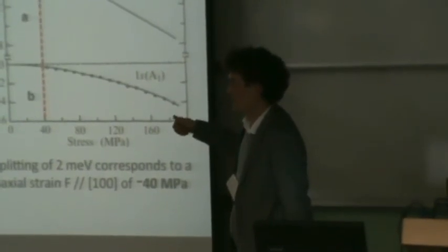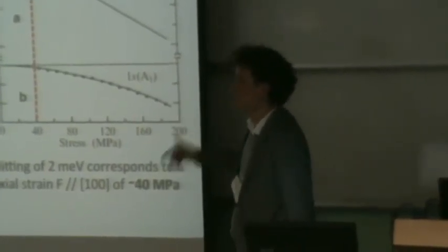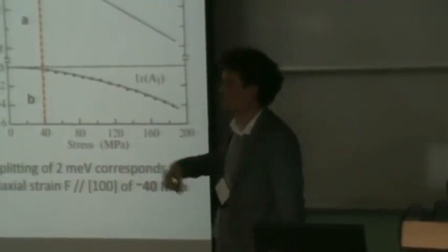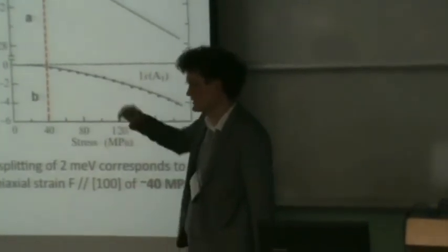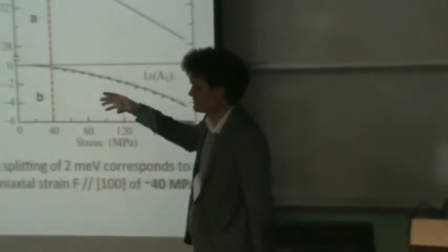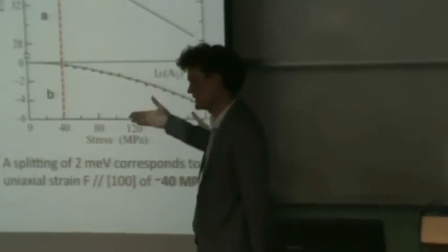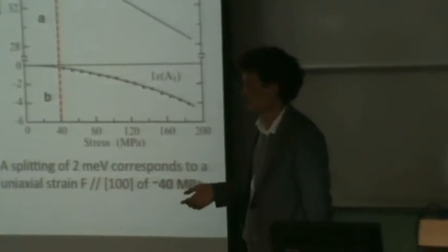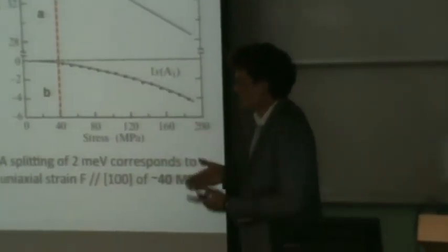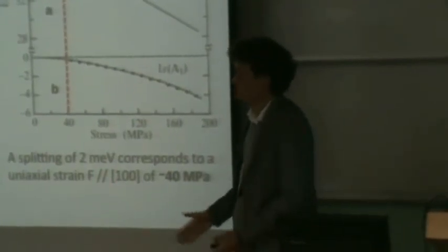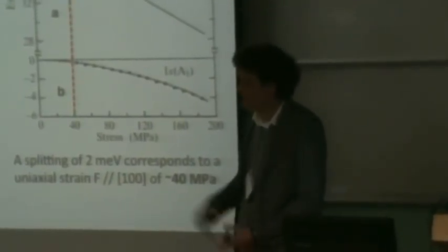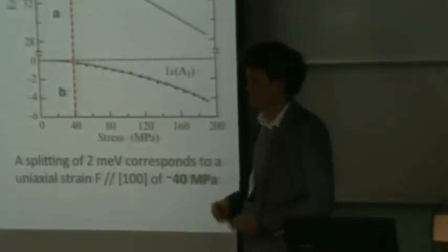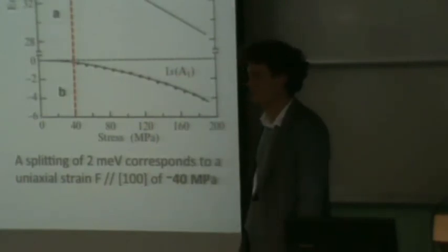In these measurements, we've got quite a large background current going through the device, and we slightly perturb that background current by exciting a few donors. The number of donors that we're exciting through this optical process works out to be around 100 atoms. So we're already sensitive to a very small number of donors, even though we've got this huge device with current flowing everywhere. Really, we just have to narrow down the device size, and then we've got something much more powerful.